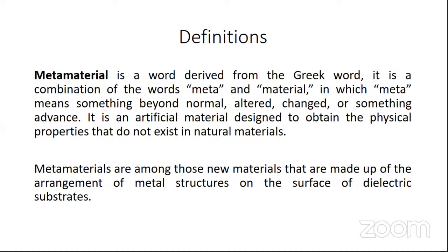This can be achieved by using high permittivity dielectric substrates, shorting walls or shorting pins, or fractal geometries. We can reduce the area of microstrip antennas using these methodologies, but they have disadvantages, such as narrow bandwidth and low gain.